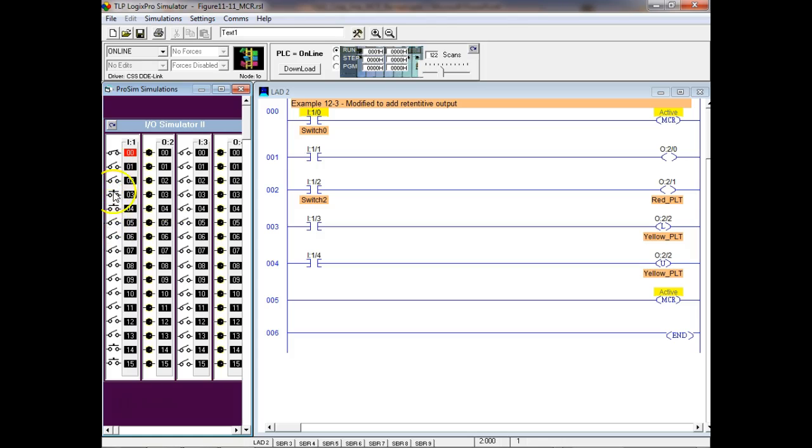Y'all understand that? Yeah. So as soon as you put a latch, you have to assign the unlatch to the same coil number. So when the guy says you cannot repeat outputs, that's not exactly true. Because I could use jumps to the same label, right? You understand? That would be the same jump with the same address, so I could use that multiple times. Well, here's one situation where we assign the latch and the unlatch because technically this is the same relay, right?